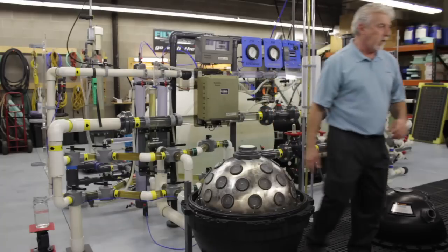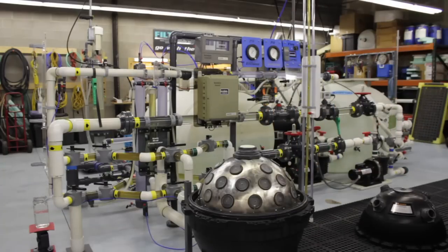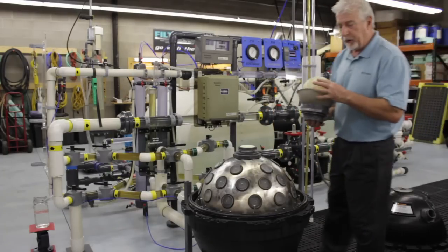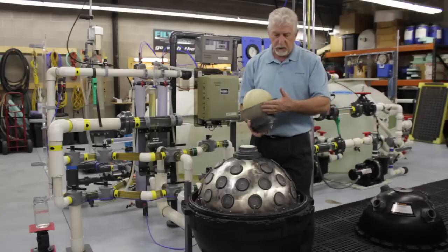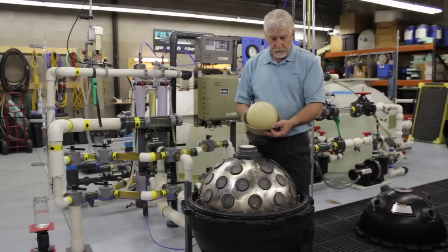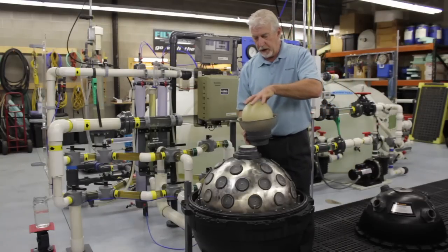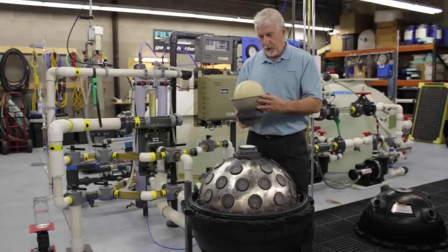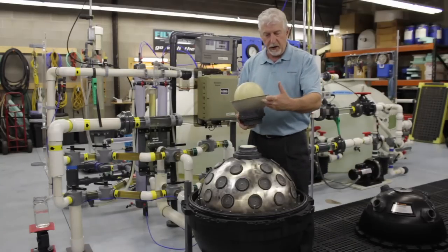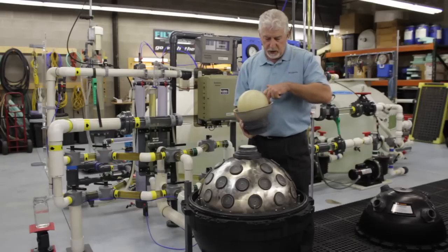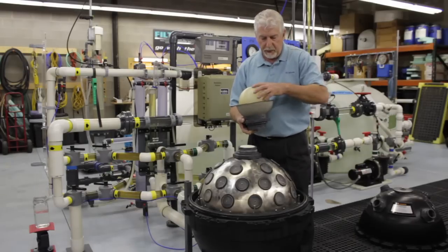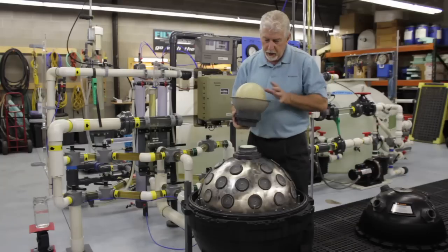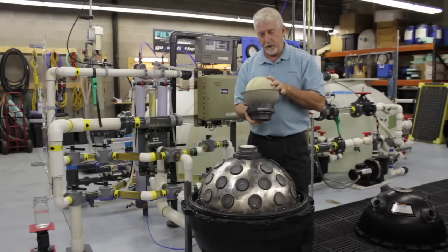How's the water collected? In the center. I mentioned the inner drain. Here it is, opened up. It's also composed of two hemispheres of double screen that are connected into a sphere at the center of the media container. As the water comes in filtered, it passes through the screen, goes in this slot between the backwash ball and the inner drain, and out the pipe at the bottom filtered.